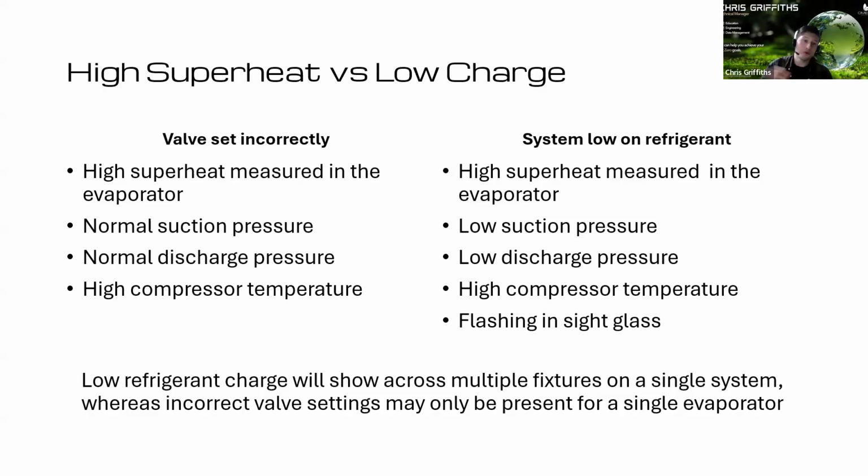Also, if you've got a sight glass to check, with high superheat you'll have no flashing in the sight glass, or ideally not. System low on refrigerant, you'll see the bubbles in there. There's just not enough refrigerant filling up that space. Your liquid is already boiled off well before it even reaches the sight glass. So that's one way of checking.